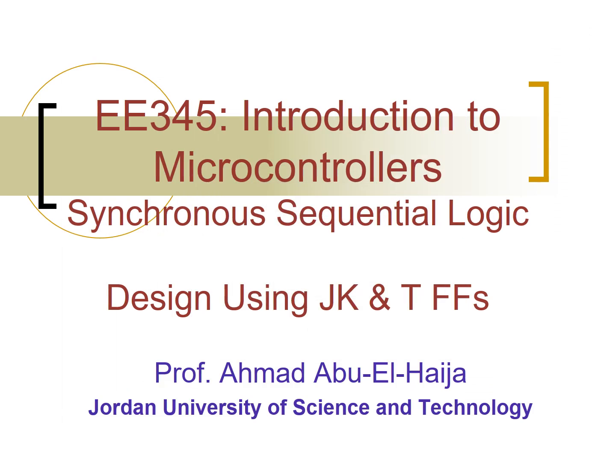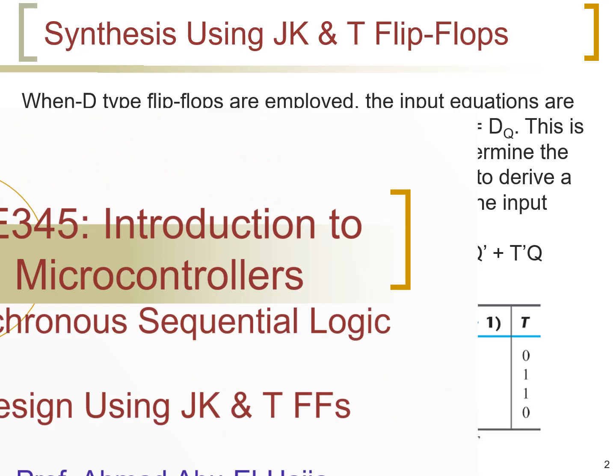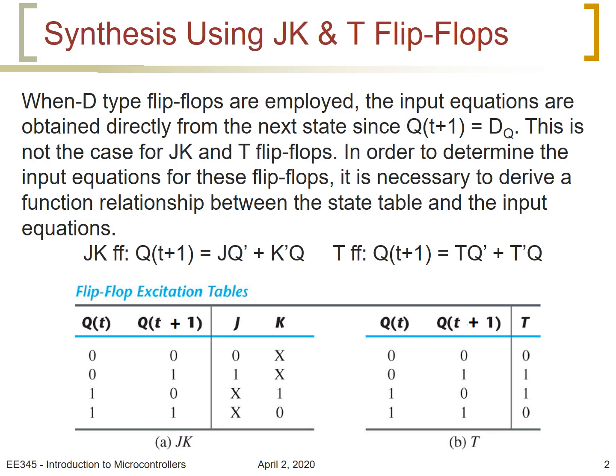Now we will present the design of synchronous sequential circuits using JK flip-flops. But before that, we would like to make one note: when we used D-type flip-flops, the input equations are obtained directly from the next state equations, because Q at time t plus 1 is equal to D of Q. However, this is not the case for the JK and the T flip-flops.